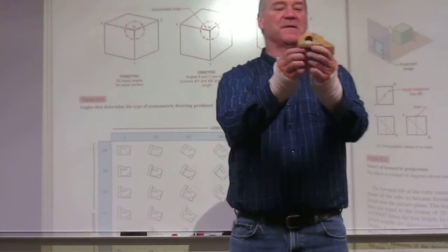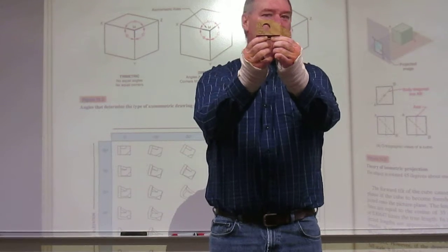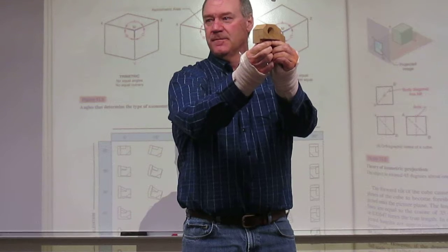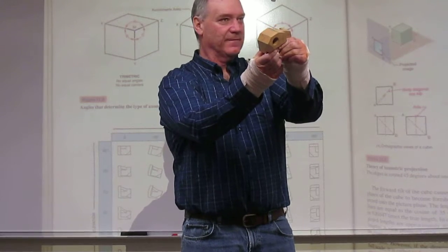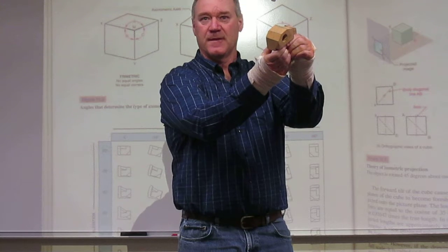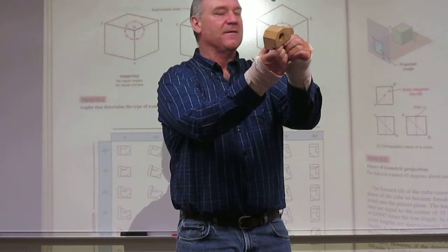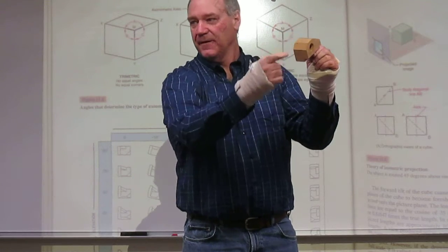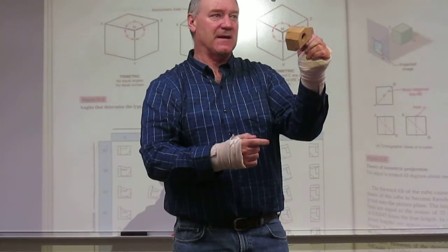Let me go to the stuff that's got more detail. Then we rotate it 45 degrees, and then we tilt it 35 degrees, 16 minutes, or about 35¼ degrees. And this is shown in your text. That creates that 120-degree angle right here on your front principal axis.